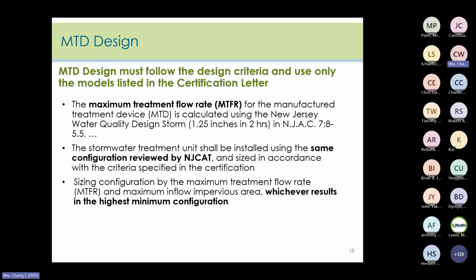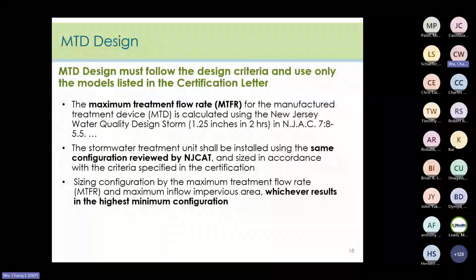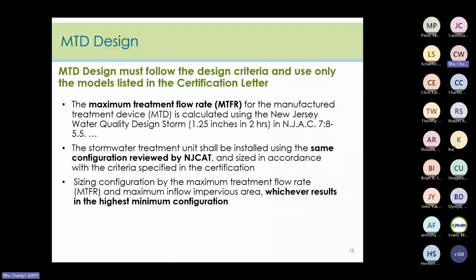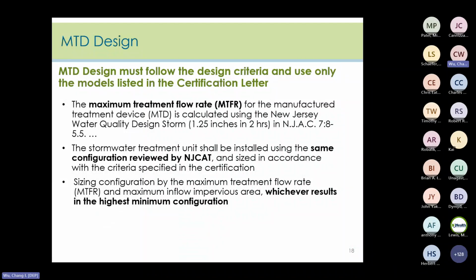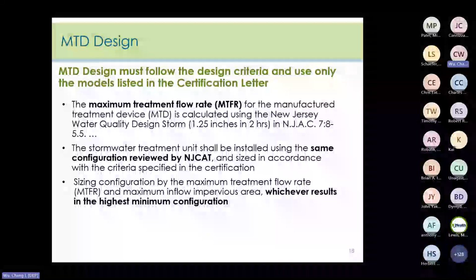So for example, an MTD has a drawing in the certification, the testing approved report, that shows only one inlet, but the same MTD shown on the site plan is to be installed with 2 inlets. Then the MTD depicted on the site plan would not meet the requirements.